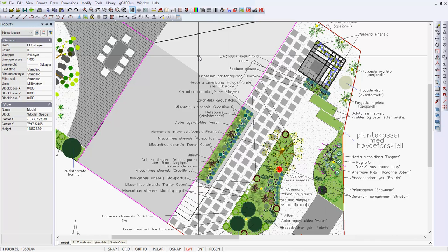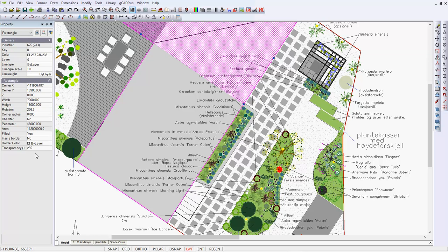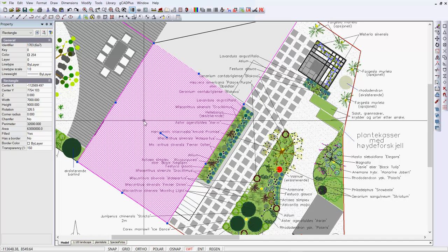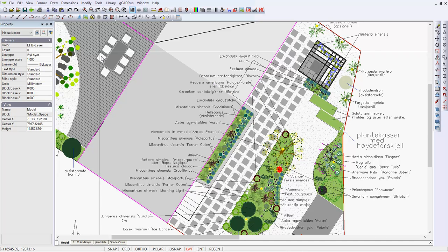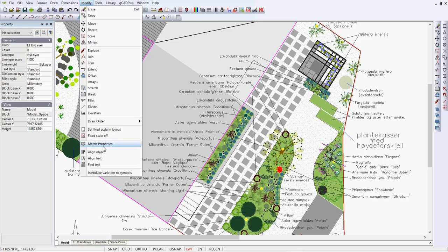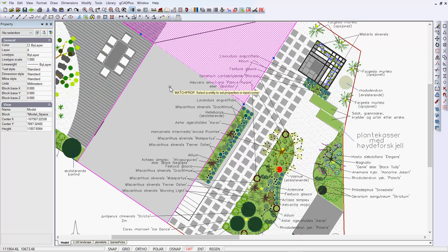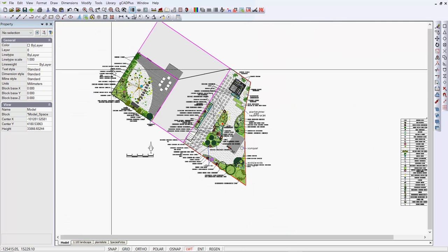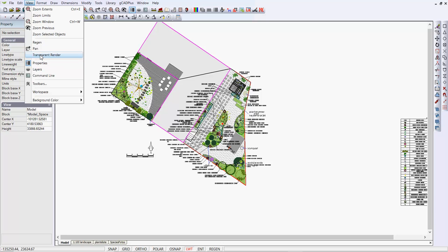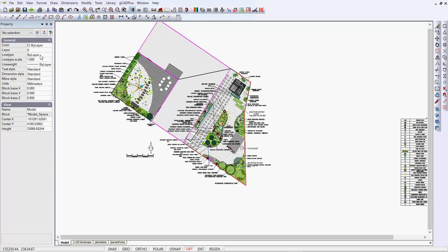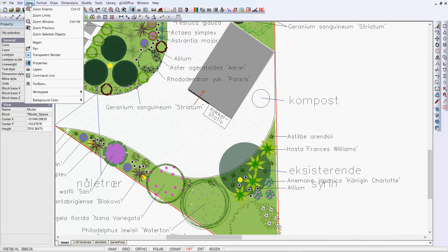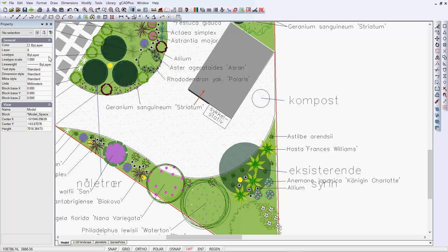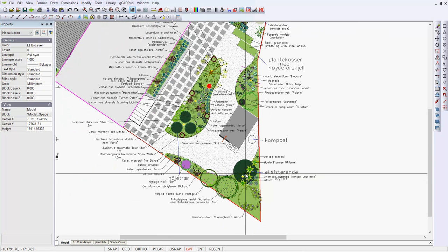And if we pick the hatching at the top here, that's 255, and this one is hatching with a transparency of 150. So we can use modify and match the properties of that hatching to there. And what I'm hoping now, if we zoom out and we say View, we'll turn on Transparent Render, and we see very little change, although something flickered down in this area here. So let's do it again, and Transparent Render. Yes, it's this other symbol here, so let's pick it.